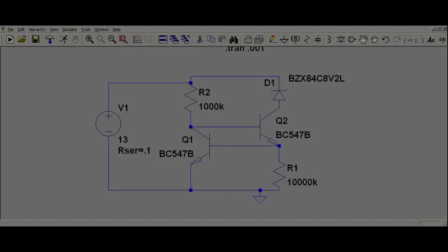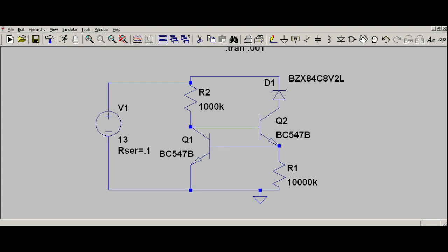In order to better compare the actual leakage on different zener diodes, I need a very small current sink, the smallest one that I can make at home without buying very expensive instruments. So I fired up the LTspice circuit simulator and drew the simple 2-transistor current sink where I've used the biggest resistor I found in my parts bin, a 10 megohms one.